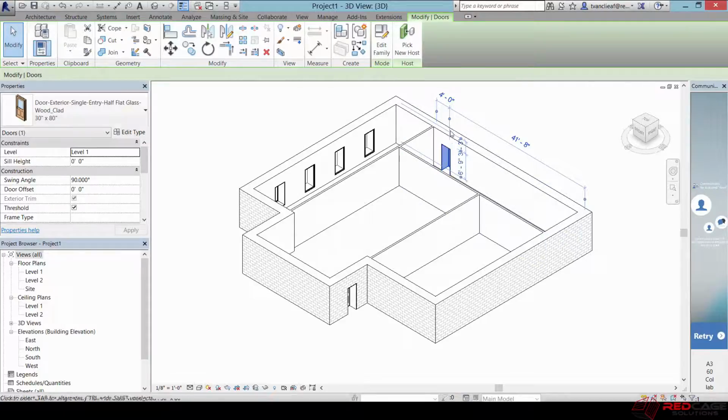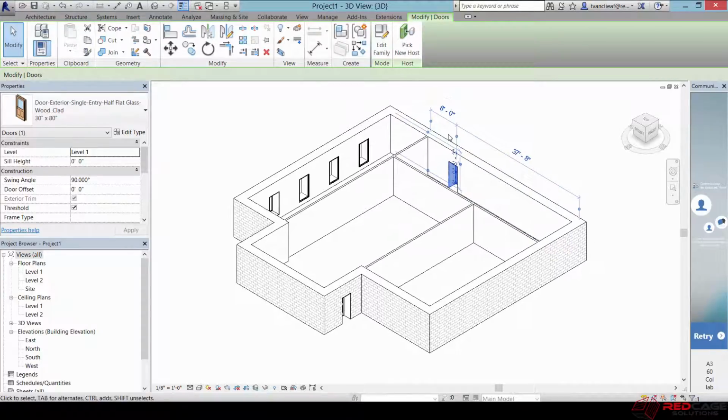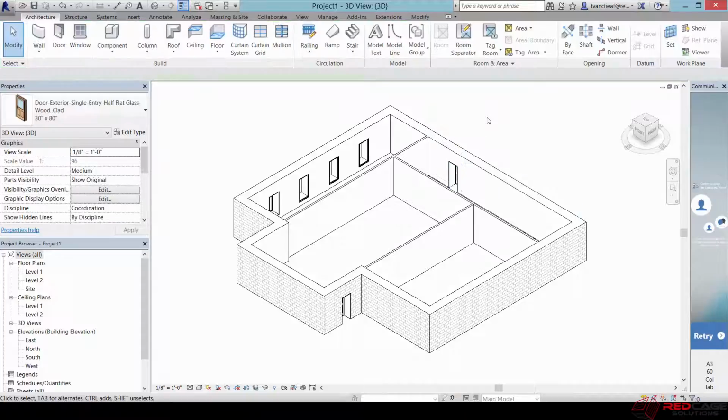So again, if I take this door here now and I multiply that by 2, I can put in formulas. So we'll say equal 2 times 4 feet. You can see how parameters can really impact your speed. You can leverage these quite powerfully.